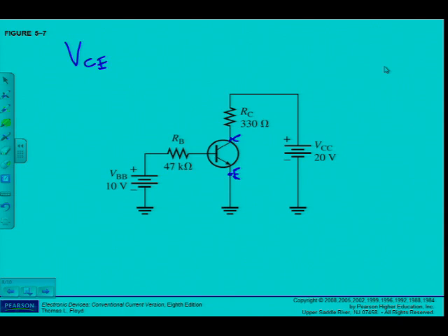If I measure with a single subscript, like VC, I measure with reference to ground. Always with reference to ground. Start reading from the left. I will put my red lead of my multimeter on the collector and my black lead on ground, but you will see that VCE and VC are going to be the same because there's no resistor or anything between the emitter and ground. So in this case, these two values will be the same. Not always true, as we will see a bit later.